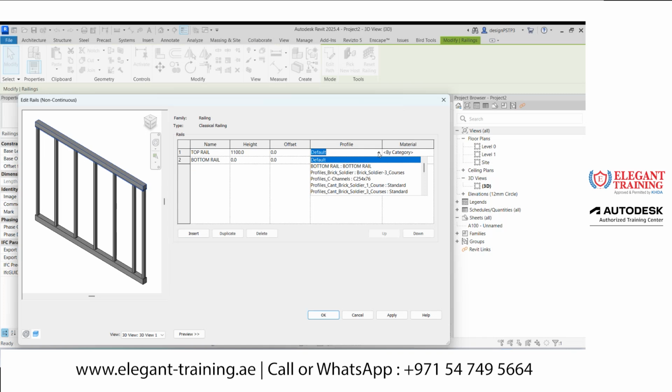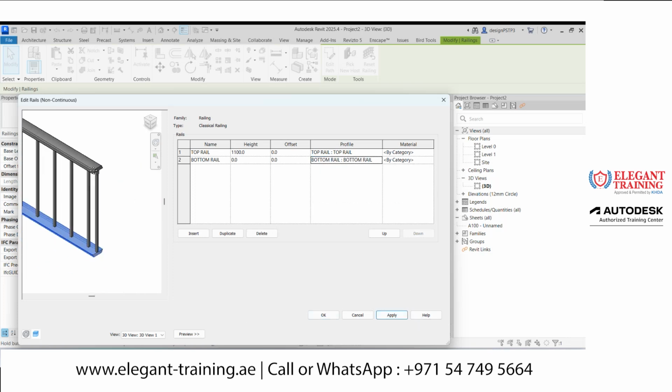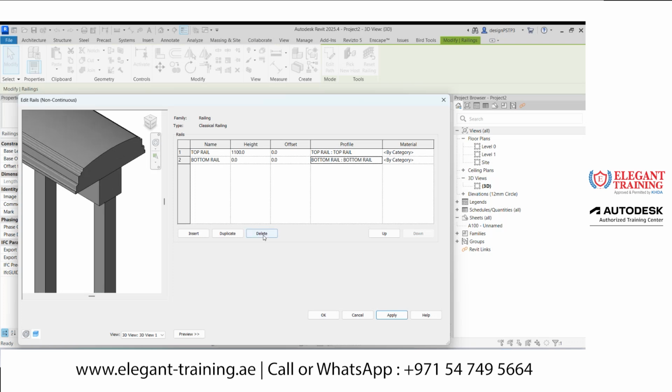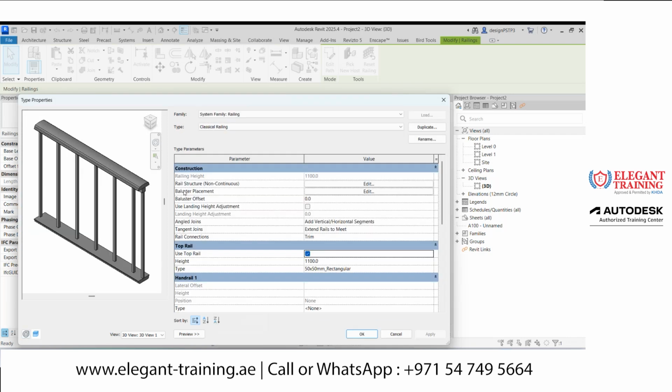Okay, the profile. Let's choose the profile we loaded, the top rail. Click apply. So the top rail is already loaded here. Same thing for the bottom rail. I choose the bottom rail and click apply. So it's applied to the bottom one. By default, there will be a top rail here that we will remove. So I give OK to this part because my top rail and bottom rail are ready. I will go to the baluster placement.